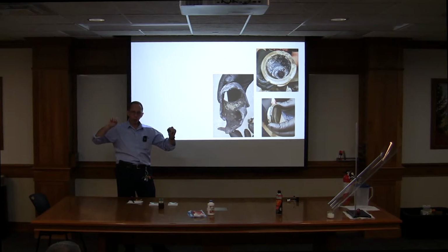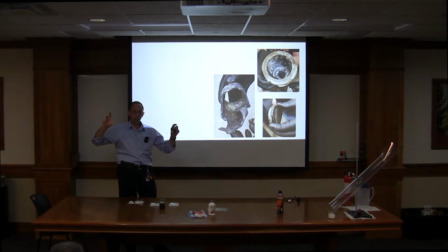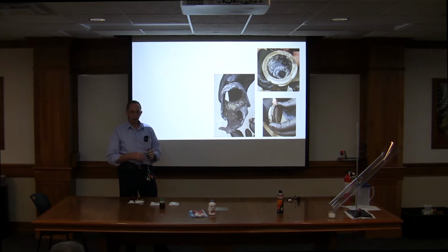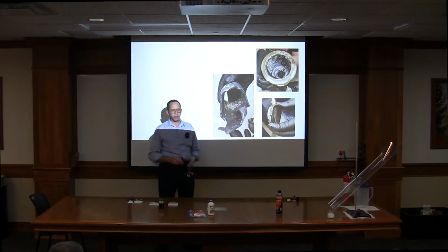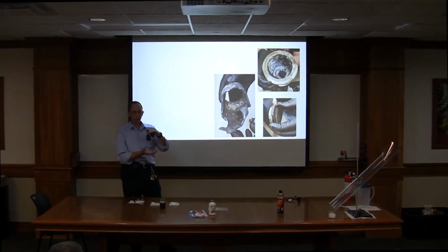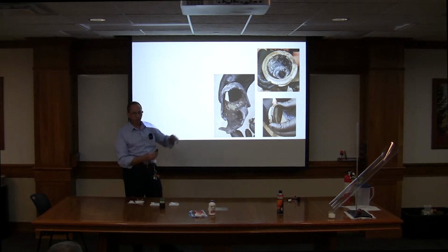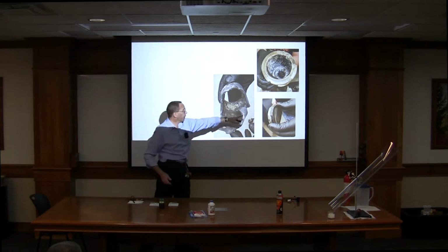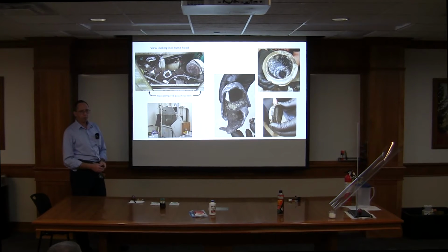As you melt it, where does that other 1.1, 1.2 grams go to? It's got to go somewhere, so it expands. Well, what happened in this incident was they packed that stainless steel vessel full of aluminum chloride, didn't leave any vapor headspace on it, and then put it on a hot plate and melted it. And when it reached its melting point, the pressure inside there blew the thing apart and destroyed the fume hood.